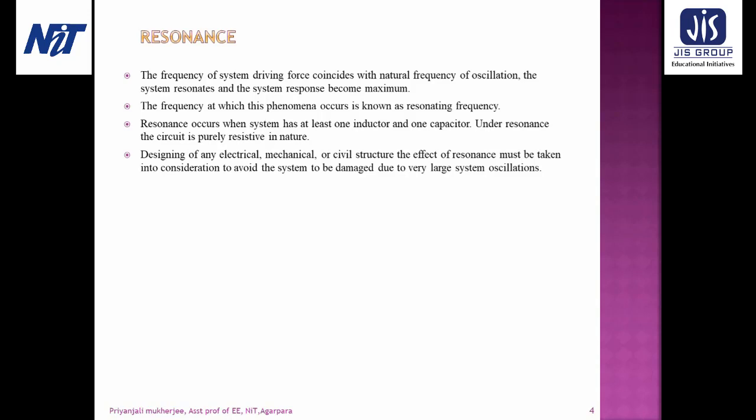In an electrical system, the resonance occurs when the system contains at least one inductor and one capacitor. And under resonance, the circuit is purely resistive in nature and is termed as a resonant circuit or the tuned circuit. And in designing of any electrical, mechanical or civil structure, the effect of resonance must be taken into consideration to avoid the system to be damaged due to the large system oscillations.